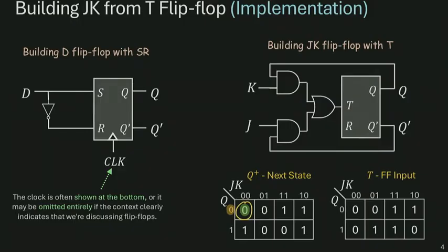The T flip-flop has to hold to realize the 0 to 0 transition. And therefore, I put down a value of 0 in that K-map. I just have to do this analysis one by one. For each condition, I do such an analysis.